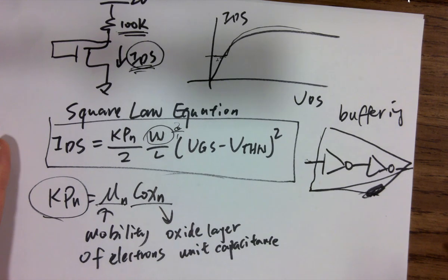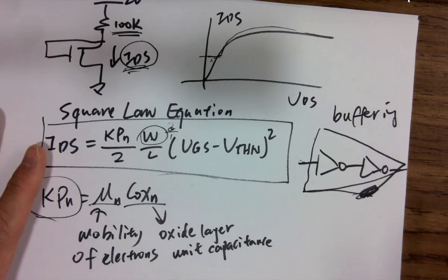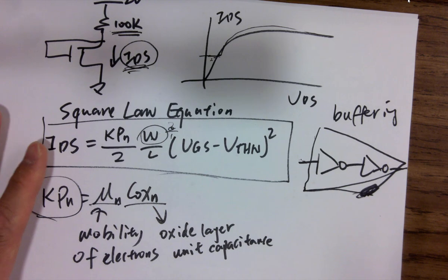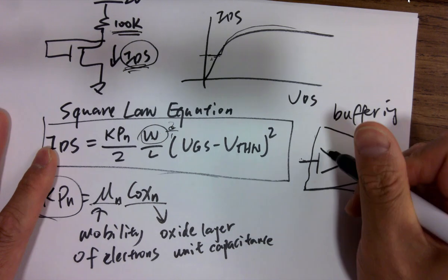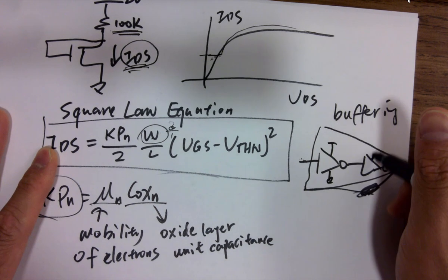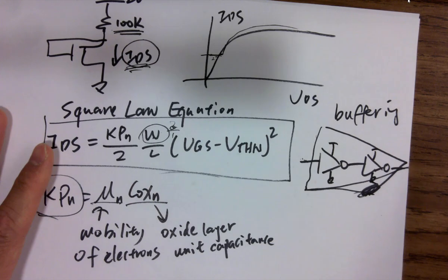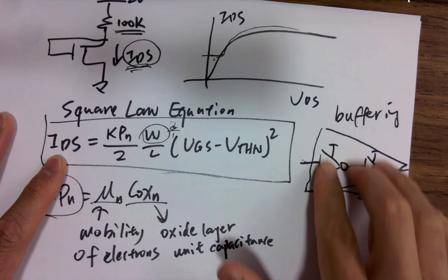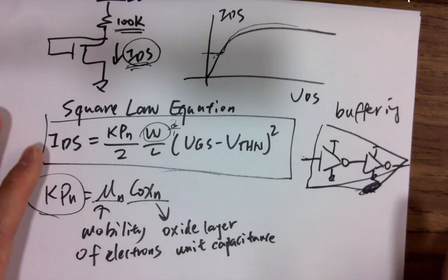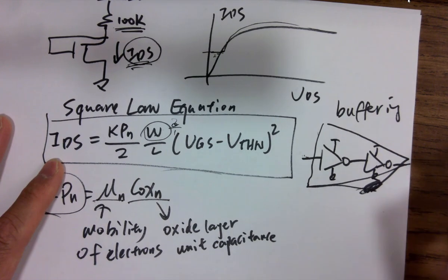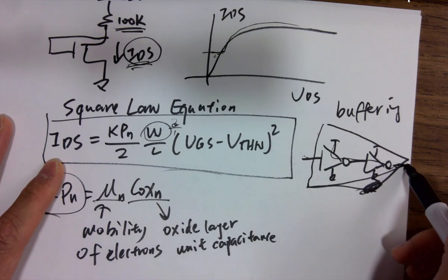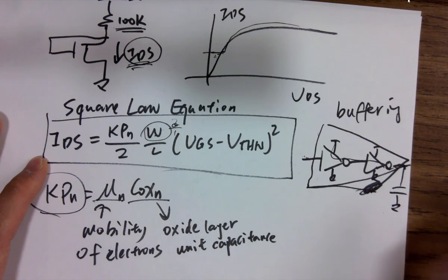It's inverting it twice. It slows it down, doesn't it? It slows it down, but the key point is every inverter has a VDD and ground. So you're just having more connections to the source, and eventually these will drive the load capacitance.